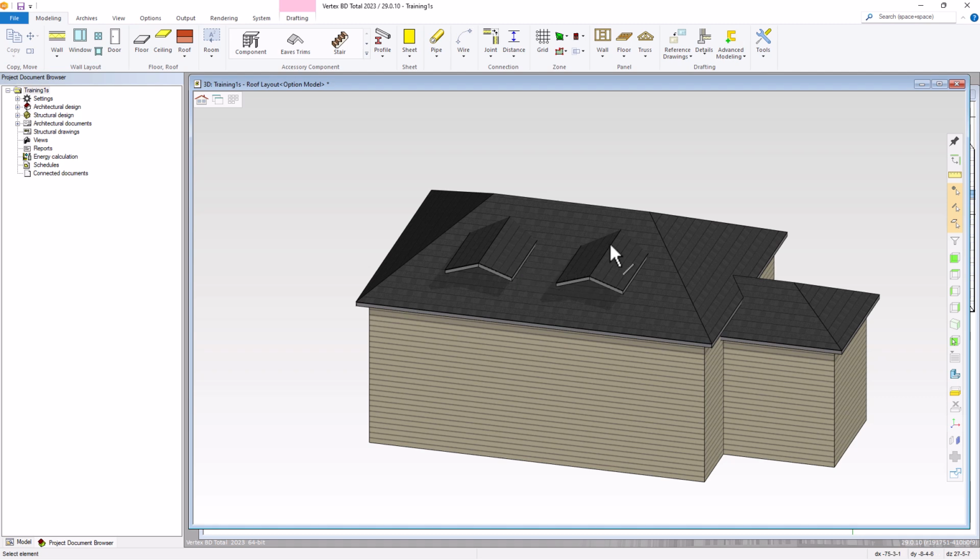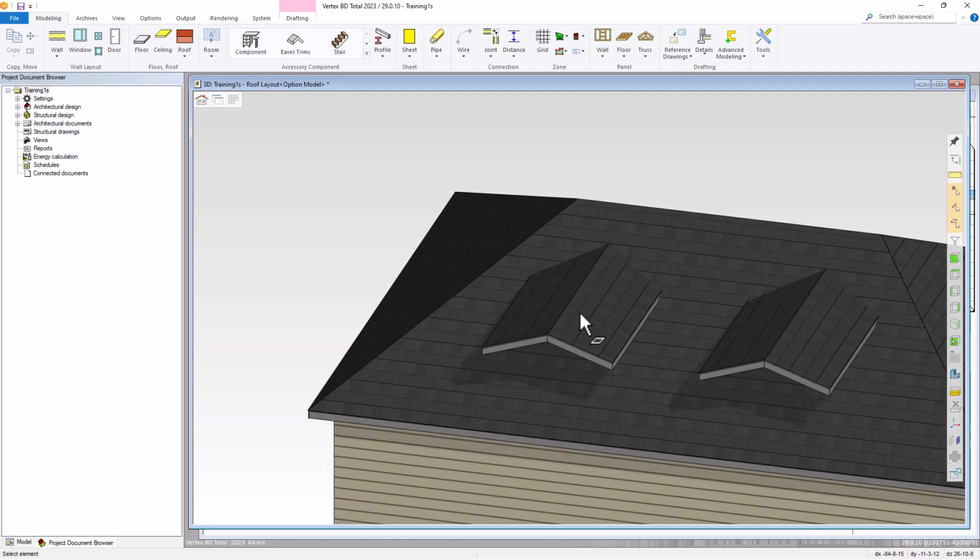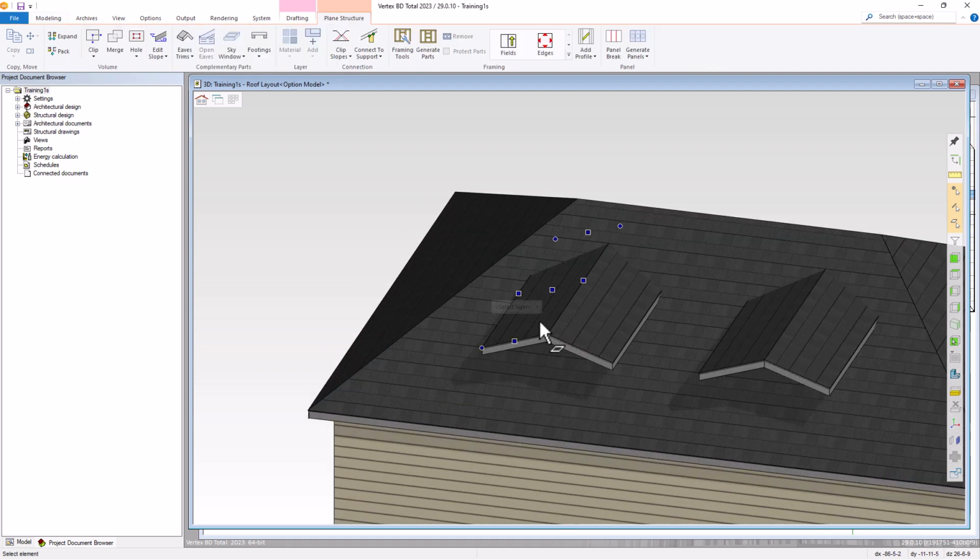We're going to clean up the roof intersections. We'll make the left dormer a true dormer and create an opening in the lower roof. The right dormer will be a false dormer, and that'll rest on top of this roof plane. Now to edit this left dormer, we'll work with that one and we'll zoom in. Select the roof, take Control key to select the other plane. We're going to cut the roof so that there's an opening below the roof dormer, and it also cleans the planes that are extending past this lower roof.